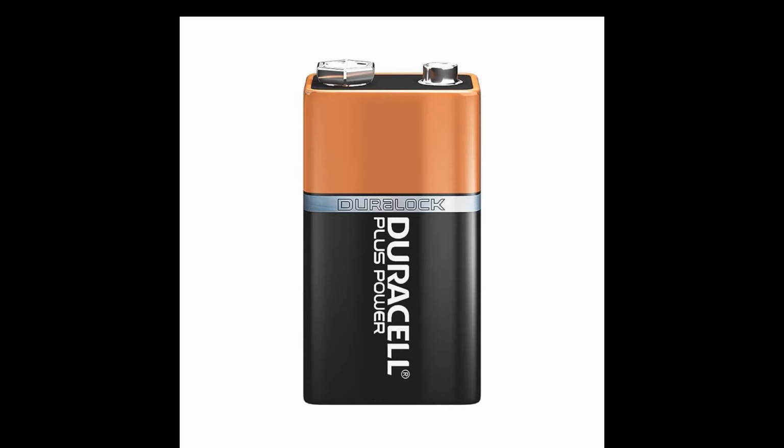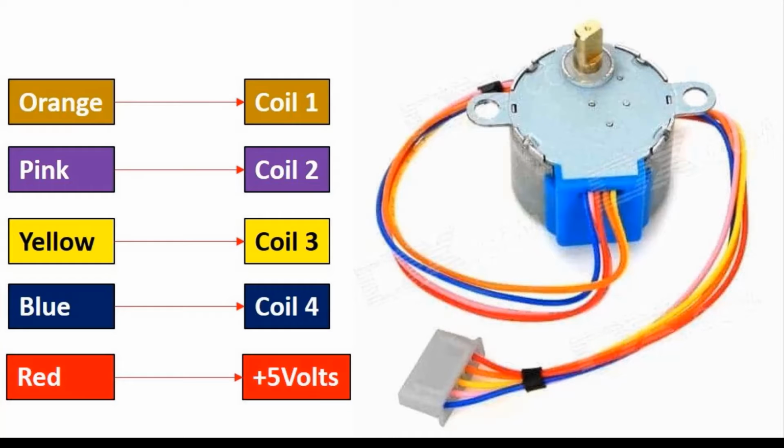We will power it with an external 5-volt supply. The following figure shows the pinout diagram of the stepper motor. It consists of 5 pins. Out of these 5 pins, 4 pins are used to provide sequence logic to the coils and 1 pin is the plus 5-volt supply pin.